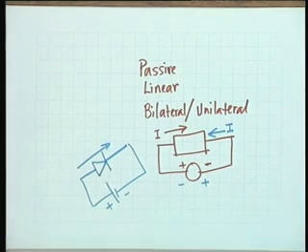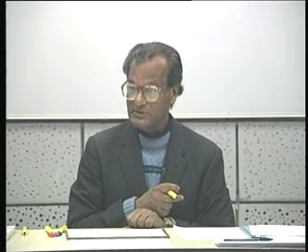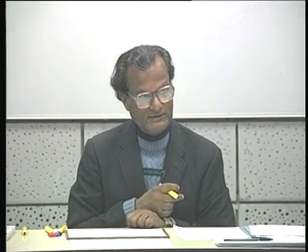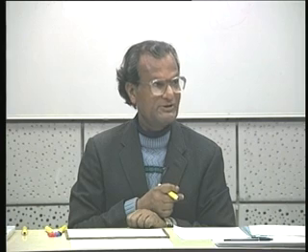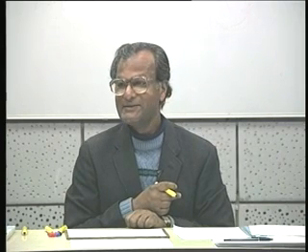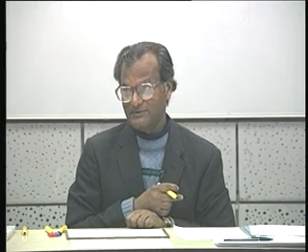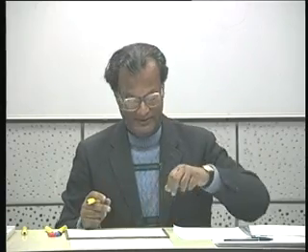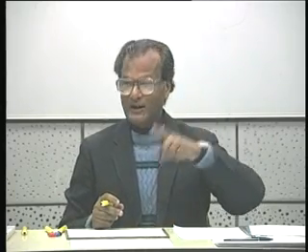If I now ask you whether a transistor is unilateral or bilateral, your answer should be, the question is ill posed, because it is a three-terminal element. All right. But if I say between emitter and base, is it unilateral or bilateral? Yes, it makes sense, it is unilateral. What about between collector and base? Okay, collector and emitter? Unilateral. And what is the reason?